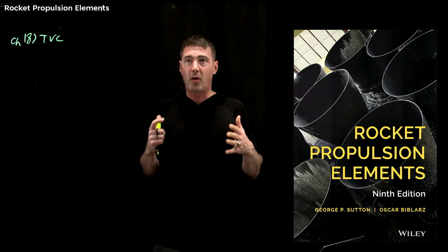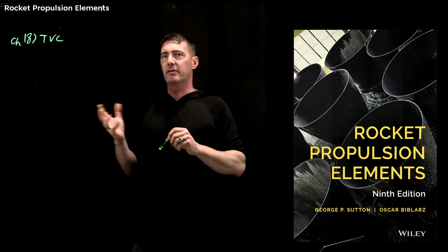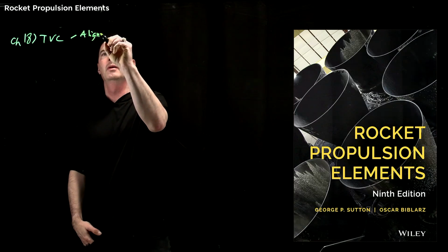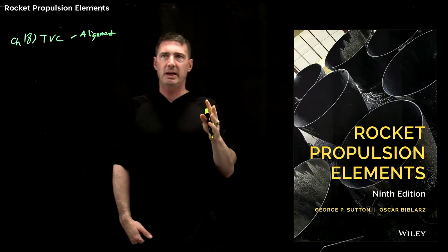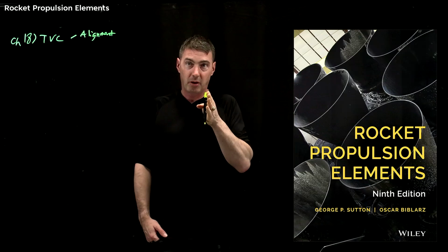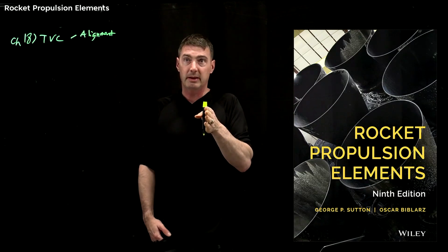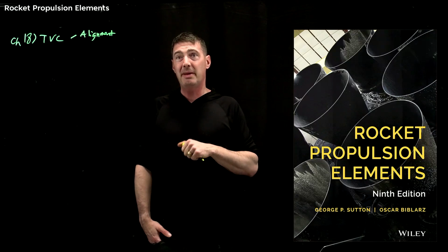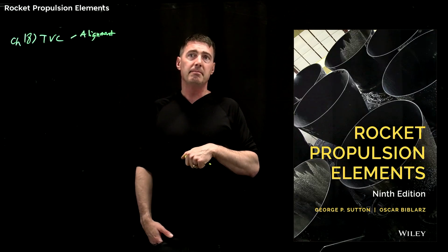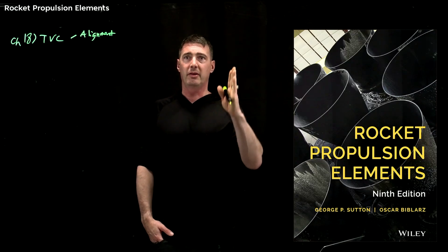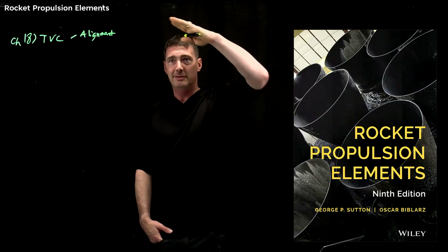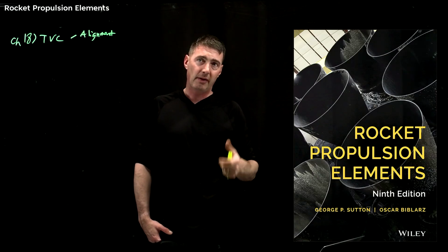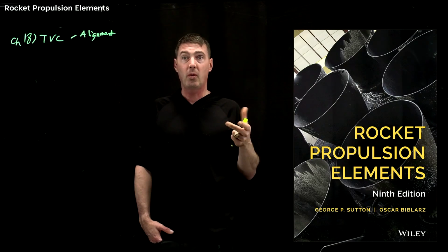Okay, and this is all about a couple of things, a couple of reminders. There's alignment. It's guaranteed your rocket engine's not going to be perfectly pointed straight back. Perfect doesn't exist. You're always going to have some deflection, and that deflection can be half a degree, and that really stacks up. A half degree will eventually completely turn the rocket over and you're done. So you have to have a way to control and adjust for it.